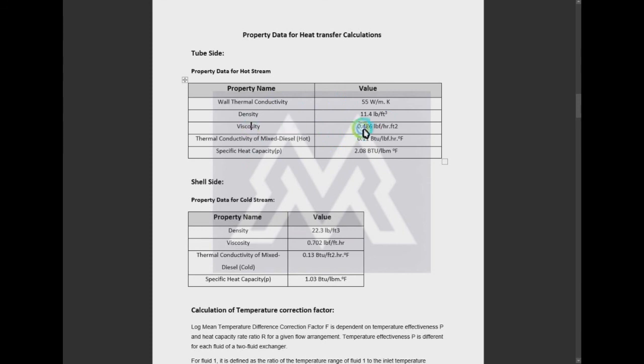For example, for calculating the average viscosity of a mixture, we have to use the mole fraction multiplied by the individual viscosity multiplied by the square root of the molar mass, with an additional factor multiplied and divided here. So it depends upon the type and nature of the system how the properties will be averaged to find a cumulative single value.